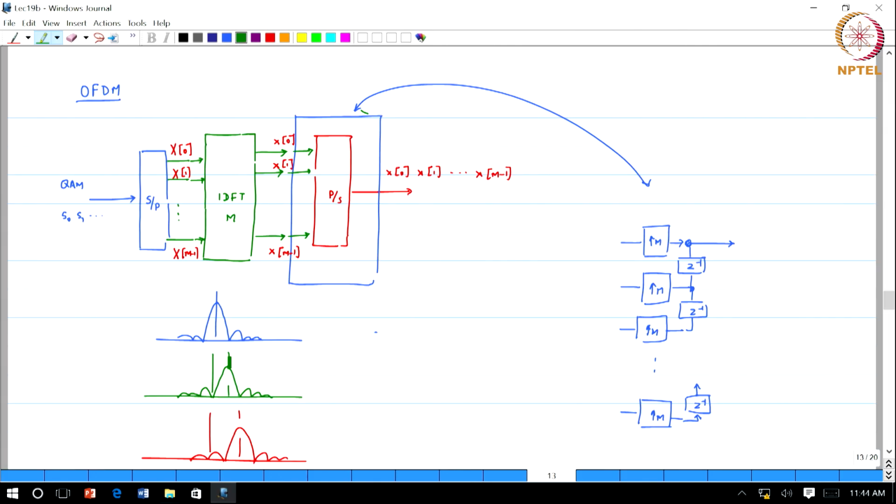Okay. So, in other words, the tools and insight that we have developed in our multirate framework say that the IDFT is actually not just a transformation, it is actually a filter bank. The underlying filters are a DFT filter bank, they basically span from 0 to 2 pi.